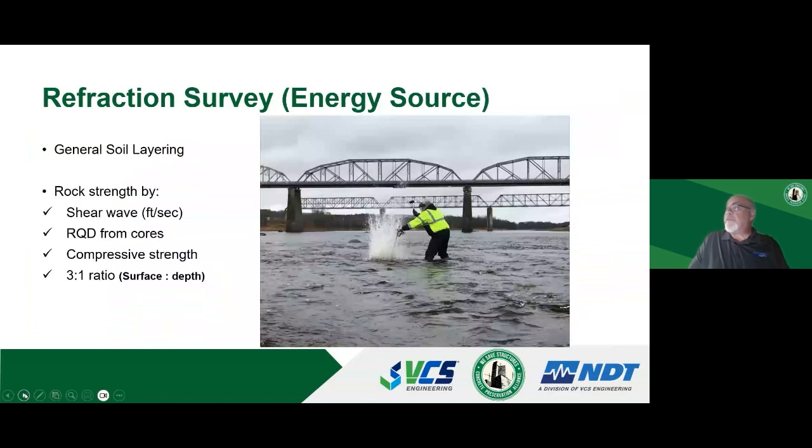An example of where this is good is in a river environment. This happened to be about knee-deep water. Wouldn't be able to really float a barge, and driving a track-mounted drill rig to get subsurface information would be very challenging. But in a short period of time, we were able to get a continuous line of data on where the bedrock was, the depth and the strength of the bedrock from the shear wave velocity.